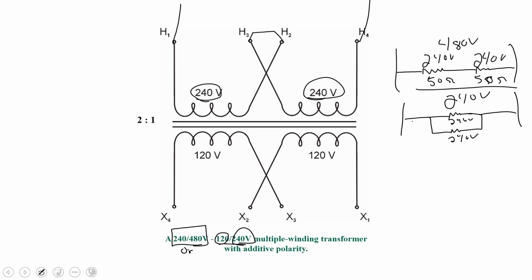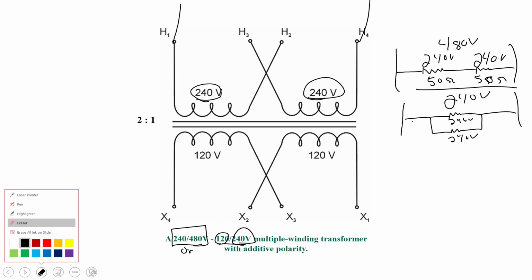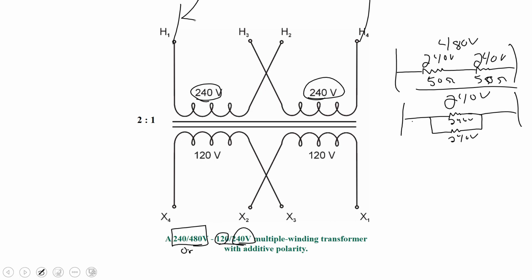Well, this same concept applies to the primary of our transformer. If I have a 240 volt supply, now across the top, I would connect these up in parallel. So now, if we look, here's line 1, it's attached to H1 and the start of the second winding, which is H3.